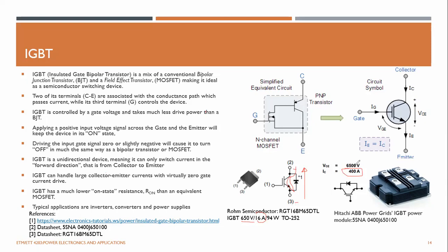large power device, you can go with this kind of module. These kinds of devices are used in power grids, so they can withstand higher voltage at the collector-emitter and drive large currents. Okay, so that concludes the operation of an IGBT. You just need to know it is a voltage-driven device.